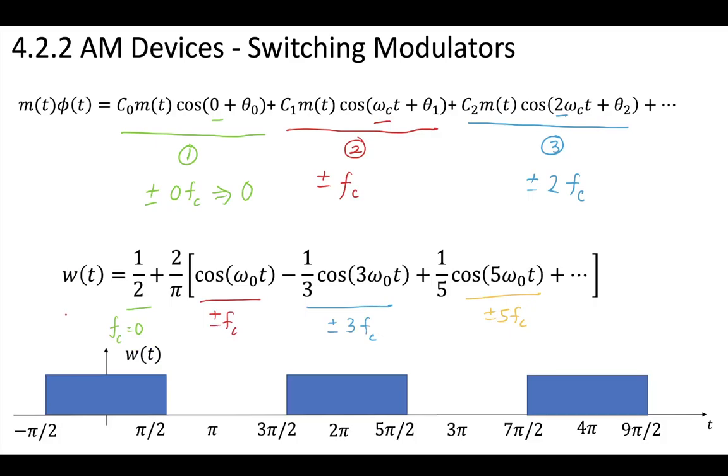So our function w(t), which we just found, we're turning a switch off and on from 0 to 1. So this is just taking a circuit, you have a source and a switch, and you're moving this up and down. We were moving it up and down at some frequency omega naught. Well, if we were able to make this frequency omega naught our carrier frequency, then you can see that we would be getting a whole bunch of terms of w(t) at our carrier frequency. So if we made our omega naught equal to our omega c, the carrier frequency, that's the same as having an infinite series of these terms, each one at successively higher multiples of our carrier frequency. And in addition to this, we have this DC term, but there's this one special term, a cosine of our carrier frequency. So if we make our omega naught omega c, we're going to get a term in here that is at our carrier frequency.